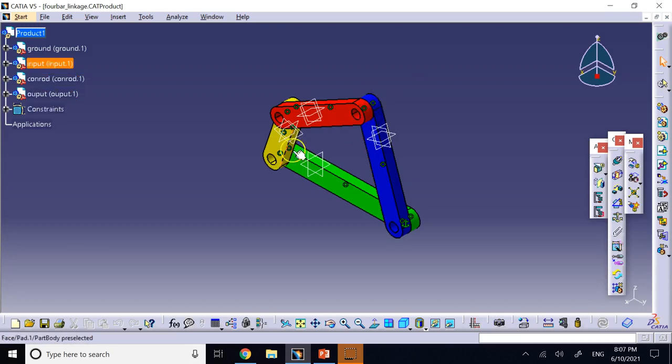You want to know, for example, if you have some specific input, then what are the outputs, what are the position, acceleration, velocity, whether linear or rotational of the other rigid bodies and so on. Generate some plots, and generate some laws for the inputs, like inputs as a function of time. Do some plotting, as I said, look at the degrees of freedom and so on. And that can be accomplished in CATIA DMU Kinematics Workbench.